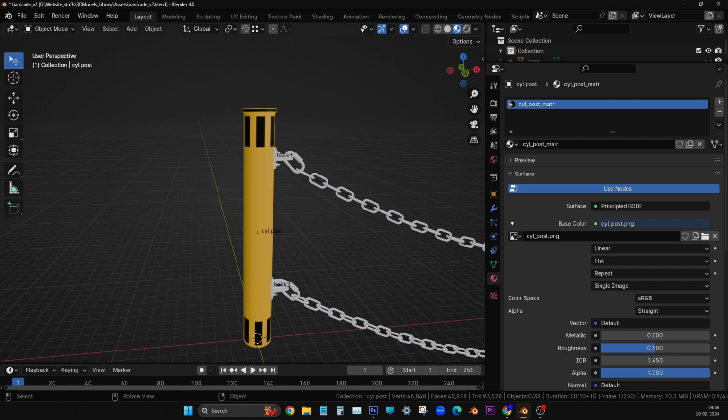Select carefully all the slaves, very carefully, and the link chains, the filler chains, are also there. Yeah, that one also. That's why I always zoom in and do it. So I think all are selected now. Last, the master chain. Shift is selected. Oh, you have selected the curve, so undo once. Just select. Control L. Link it. That's all.